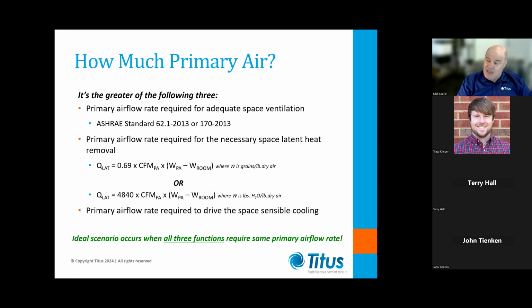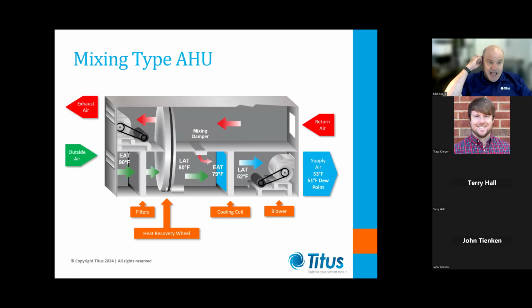So for that reason, you may be using a recirculation air handling unit, which is this type of air handling unit here. This is the type of thing you may use on an office building. So not DOAS at all. So we're going to mix return air with outside air, push it through the cooling coil there, and send the air to the building, maybe at 52 degrees saturated. Just going to pick up some motor heat and some heat from the ductwork. That is about as warm air as you're going to get away with on an office building.